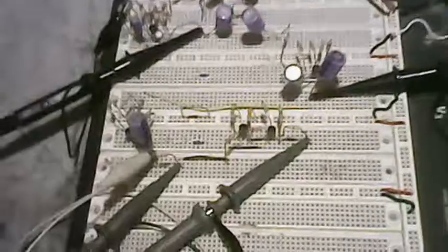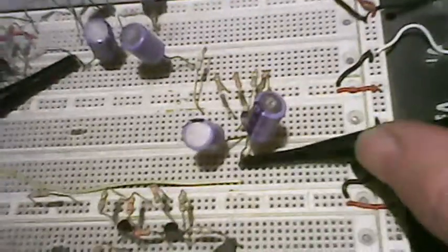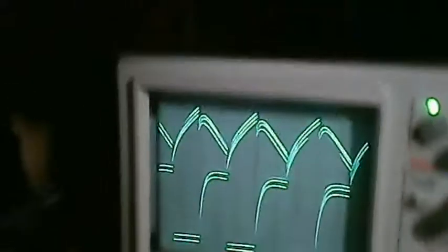Okay, so as I'm building my circuit, I have my astable multivibrator circuit I built, the integrating network to produce a triangle wave, and the amplifiers and the Schmitt trigger circuit. I'm checking the waveforms with the astable multivibrator circuit output, and I'm seeing a square wave. However, as I go through the rest of the circuitry, I'm looking at the triangle waveform as it's coming out of the integrator and out of the first amplifier. And this is my triangle waveform there.